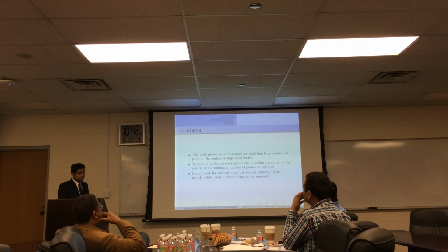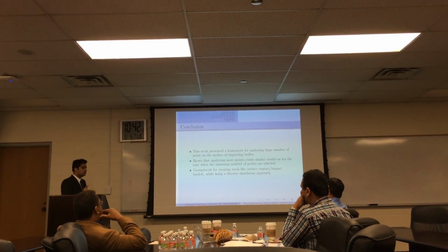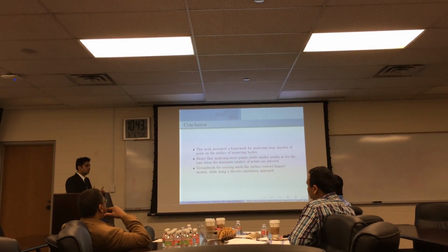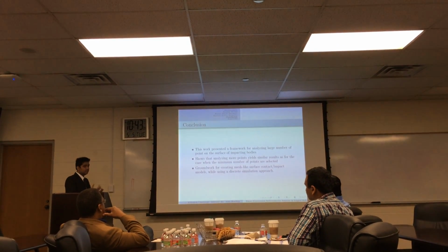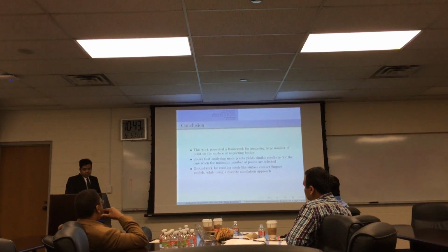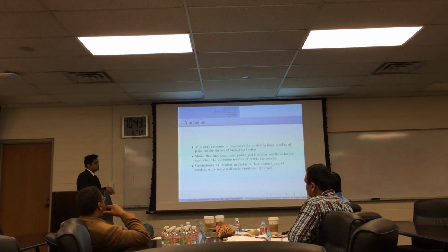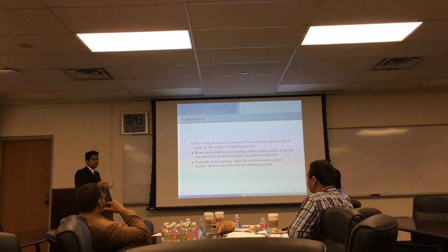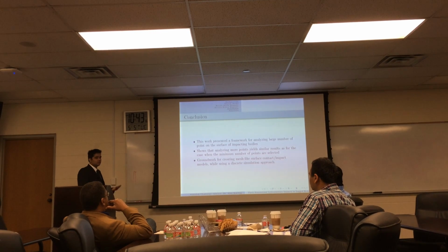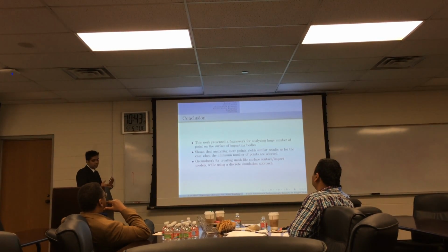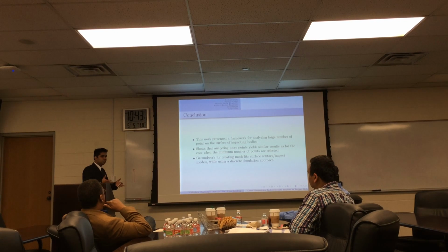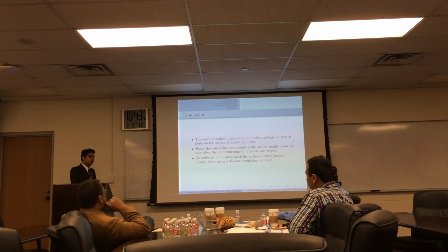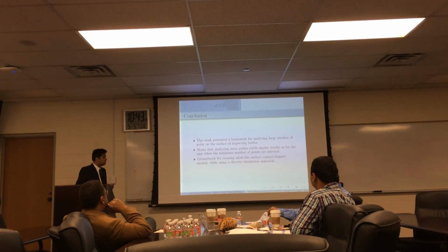It also shows that analyzing more points yields similar results as the minimum number of points if selected properly. Here I've shown 4-point and 8-point cases, but we believe this method could be extended to a larger number of points. We could have a mesh or a grid of points on impacting bodies and get accurate results after the impact event.